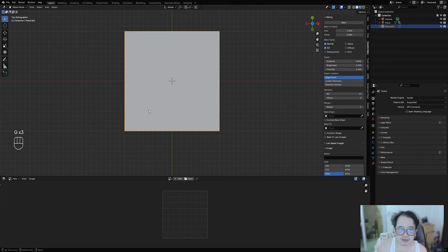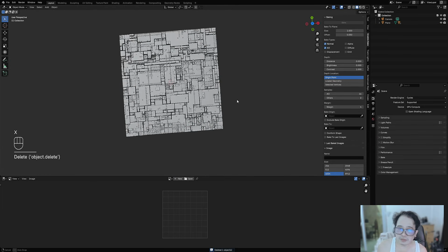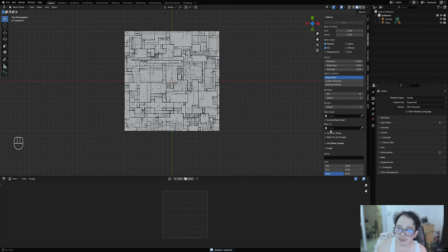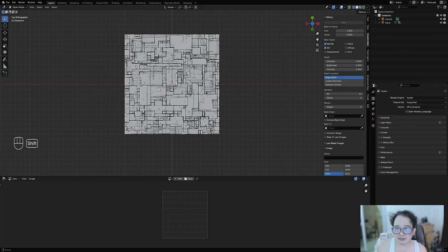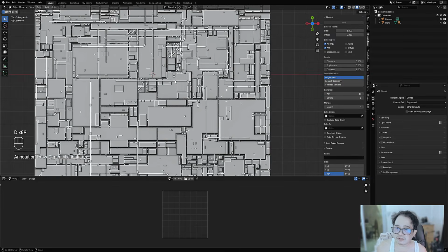So if the bake to object provided by the script, which is activated when there's no object here, doesn't work, it bakes like this with an offset. It's not really center, because the center it goes for is the average location of the vertices in the mesh, and sometimes it fails because of the way the mesh is constructed.